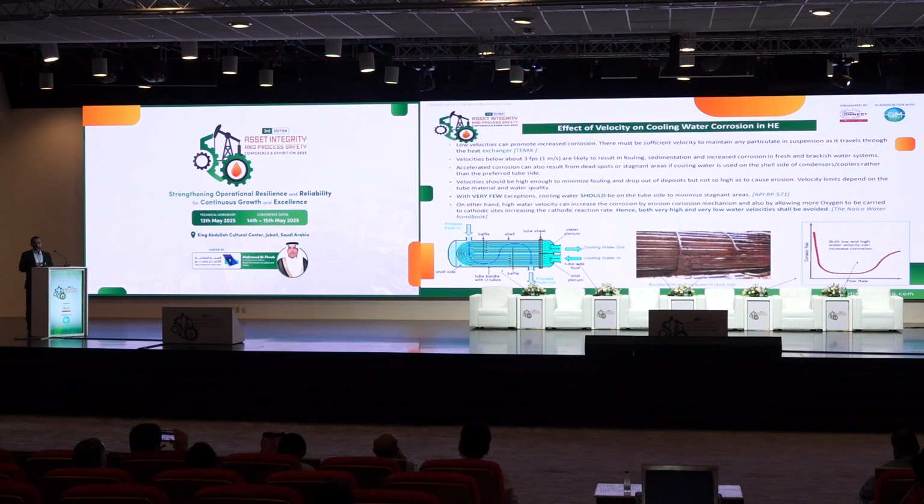In some cases you cannot do that, and you need to put the cooling water in the shell side, not in the tube side. These are very special cases of high pressure application, where the high pressure side is in the shell side because the other choice is not economical. But you need to think about allocating the cooling water in the tube side so that you can eliminate the tendency of the attack. And this issue can come from very low velocity in the shell side, and also from localized high velocity if it can happen.